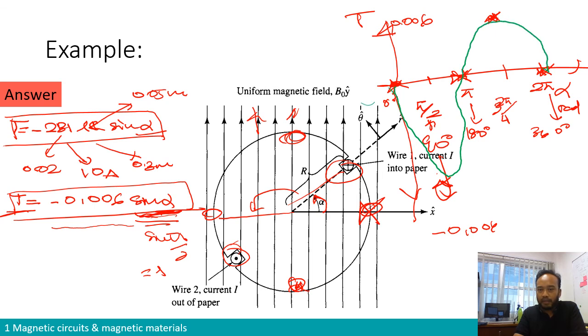So if we plot the graph, it is a sine wave with a minimum and a maximum. You have one period of torque as the rotor goes through one rotation. You will have a minimum point of torque over here and a maximum of torque over here, but you have 0 torque when you are at 0 degrees or at pi, half a rotation. This is basically expected and predictable.